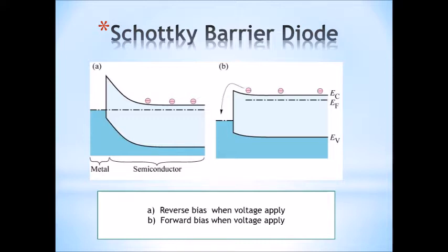If the reverse bias is continuously increased, the electric current gradually increases due to the weak barrier. If the reverse bias is largely increased, a sudden rise of electric current takes place. This sudden rise in electric current causes the depletion region to break down, which may permanently damage the device.